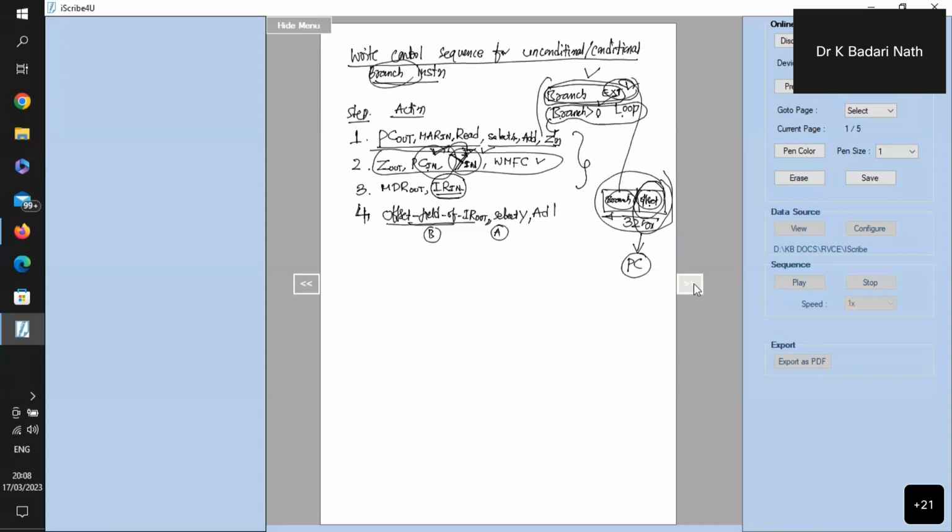So you have to give add, because you are adding to the program counter, and the answer, as we know, in the same clock cycle can be written into the temporary register called Z. So now what will happen? You are preparing the new value of the program counter. Whatever is there from the previous addition, Z out, I am writing into the program counter as the new value, and then at the end of that I say end.